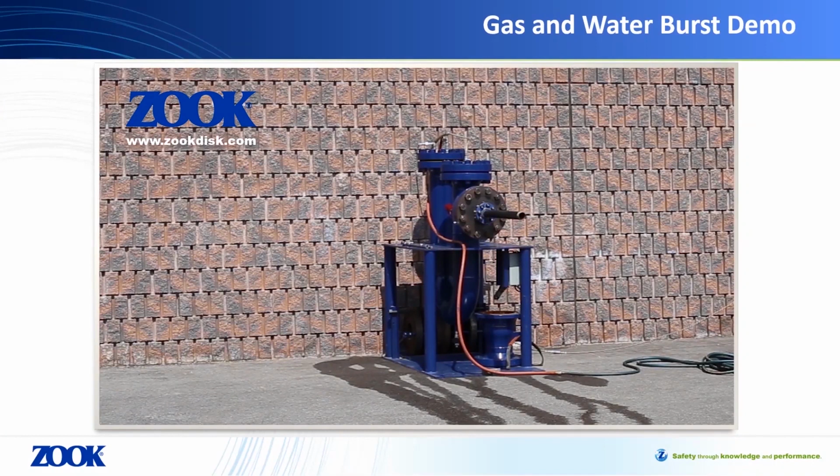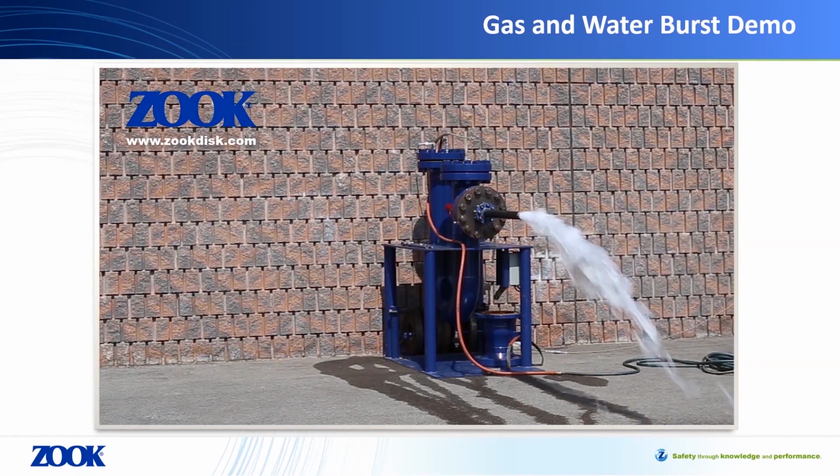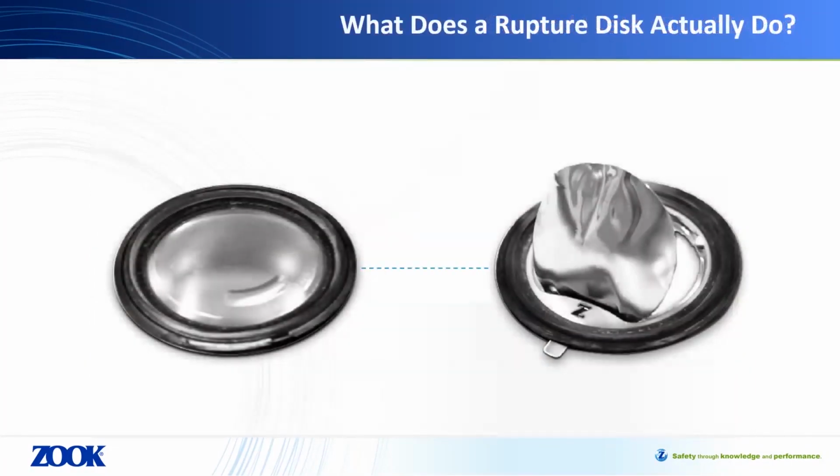Rupture discs are custom-designed safety devices. They can be engineered to function in both gas or liquid service, what we call compressible or incompressible service. As in many cases, design standards govern design and commissioning of various systems. As a rupture disc can be considered an essential safety device, they're typically designed, engineered, and manufactured in compliance with several national and international standards to ensure consistency of product and manufacturing process throughout the industry.